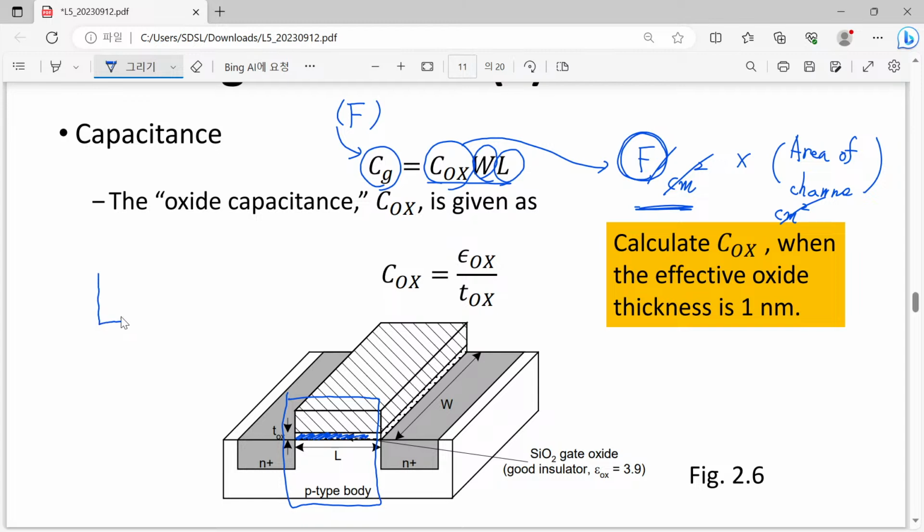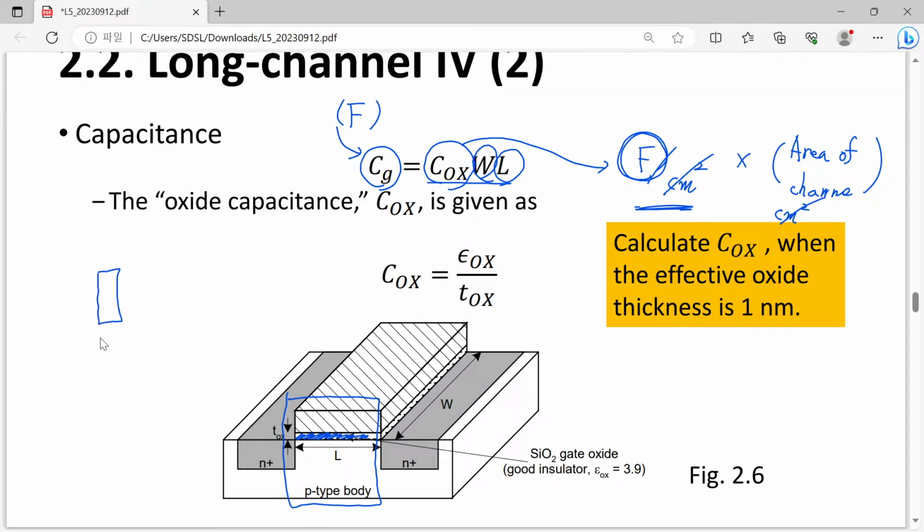I mean, think about this one. Now you have the minimum sized transistor, 2 lambda and 4 lambda. Then you will have a certain gate capacitance. Instead of that, now I have introduced a 2 times wider transistor. Let's say this is now 2 lambda times 8 lambda.